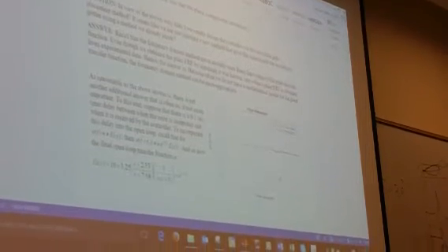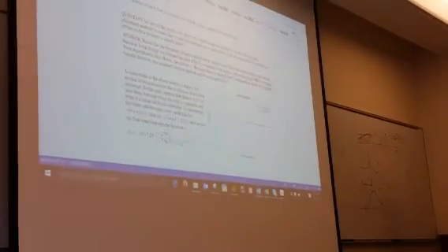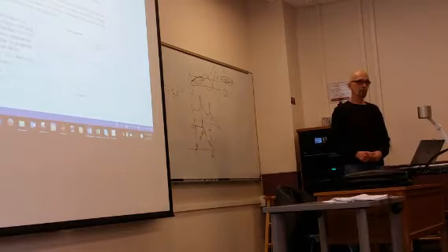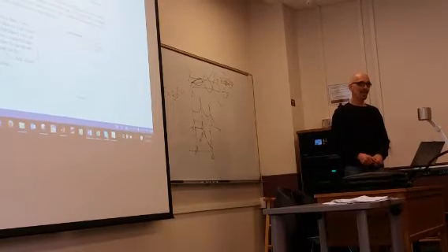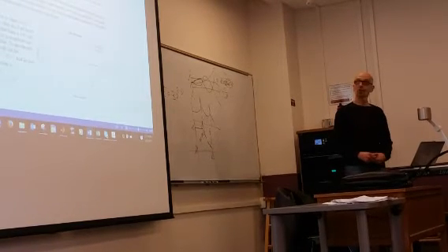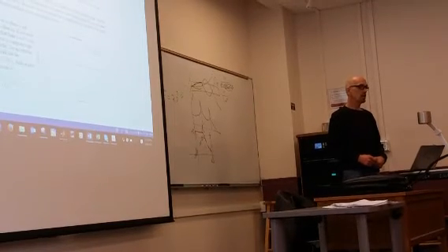Well, that's screwed. Except if you think about the silver lining here, had you not put that compensator in, and you started out with a phase margin of 18, right? So you're at minus 162. But the phase of the time delay dropped you down by 21. What would your phase be then? Minus 183. You now have a negative phase margin. You now have actually an unstable system. You don't just have a system that you don't like. You have a system that's going to crash.